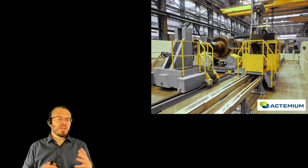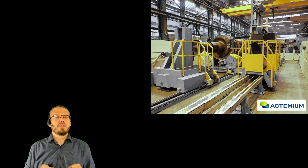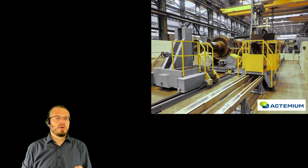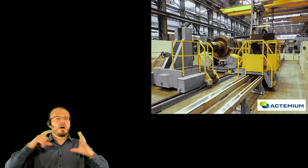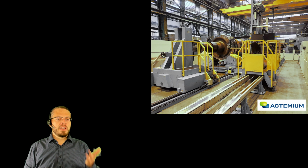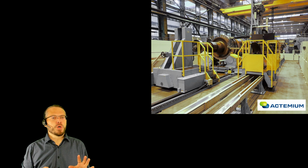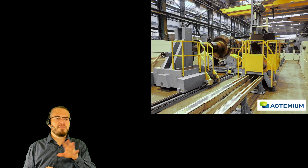And we can use that not only for those kind of small discs, which are only about 5 tons of steel. We can actually use it also for such big shafts, such generator shafts. Those generator shafts can be up to 20 meters long, 2 or 3 meters in diameter, 200 tons of steel. A manual inspection of such a shaft, I would guess somewhere within the 4-week range. Automated, perhaps 4 days. You can see a little bit the scale. If you look here at those steps going up, you see the scale of that huge shaft.